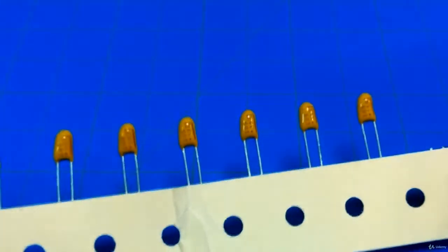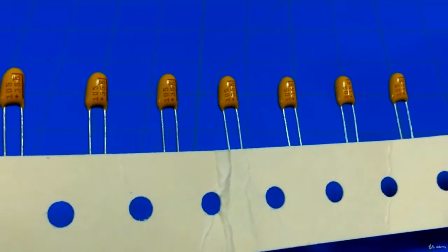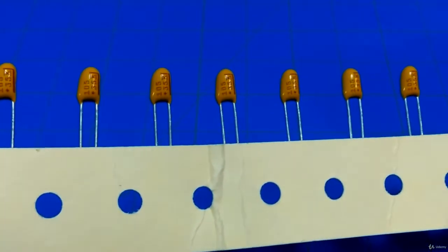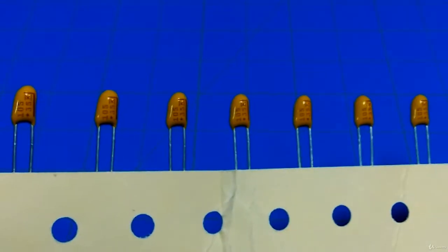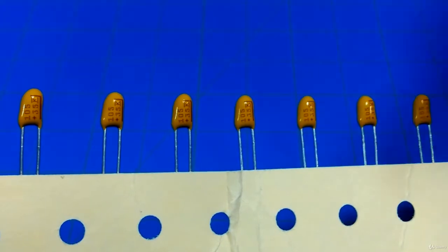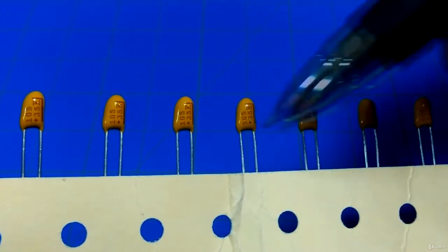Now let's take a look. There's another kind of capacitor, and there's many kinds of capacitors, countless capacitors. These are called tantalum capacitors. All right. So let me show you this. These are tantalum capacitors, and tantalum capacitors are also polarized, and you can see the little pluses. So if you look here carefully, you can see, get a little tip here, right there is the plus, the other side is the minus.